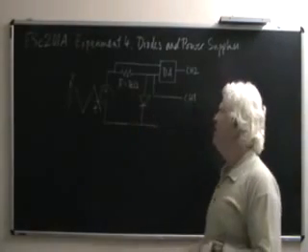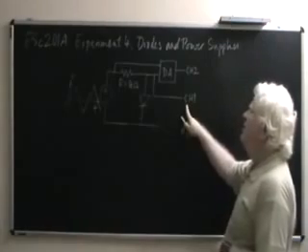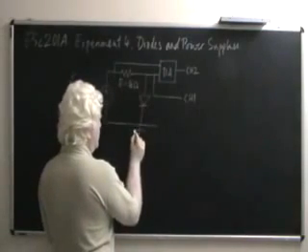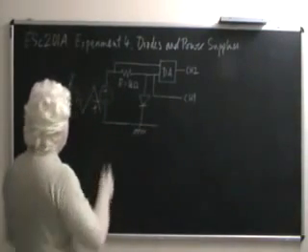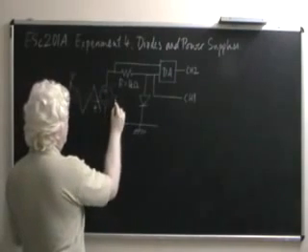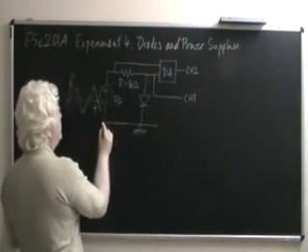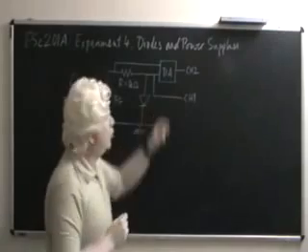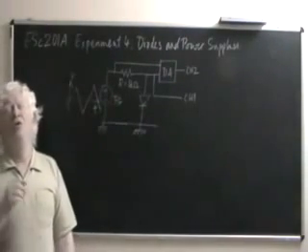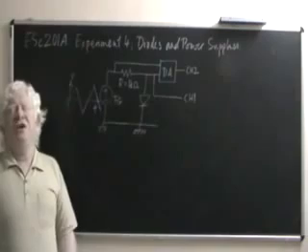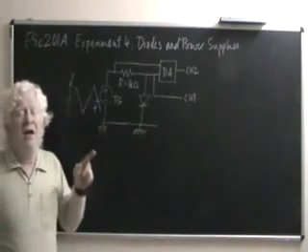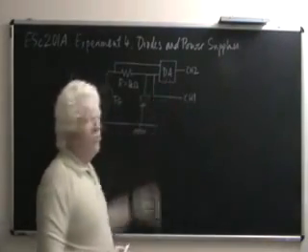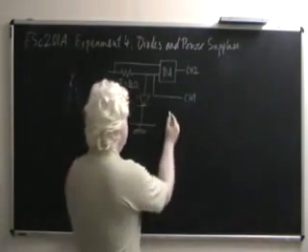So what the voltage will tell us is a number which is proportional to the current through the diode. At the same time, on channel 1 over here, we can measure the actual voltage between the diode and the ground. This part is grounded because this is the function generator source which produces a supply which is also grounded at one end, and this oscilloscope also makes measurements only of voltages which are with respect to the ground. And this is an important point. Why are we putting this thing DA over here? The DA stands for difference amplifier.